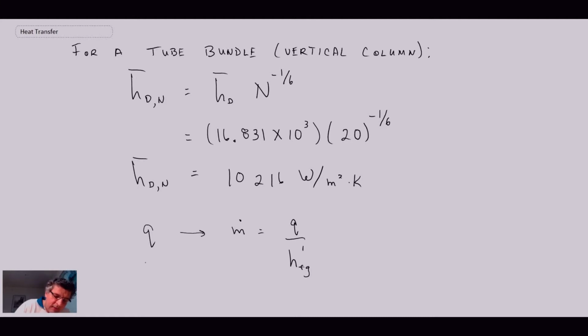First step is to get the amount of heat transfer going on within this tube bundle. So let's begin with that. I'm going to determine the total heat transfer for the condensing unit. Remember there are n by n, or 400, tubes in this bundle, and this is Newton's law of cooling.